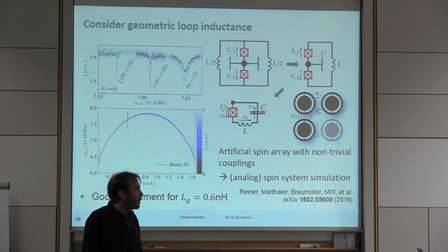And also, what's the quality factor of your resonator? Of the readout resonator? Well, it's overcoupled to the feed line, so it's about 2,000 to 5,000. But that's a readout resonator. For the flux bias, it has to be gradiometrically coupled as well.